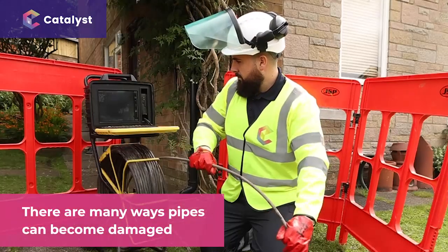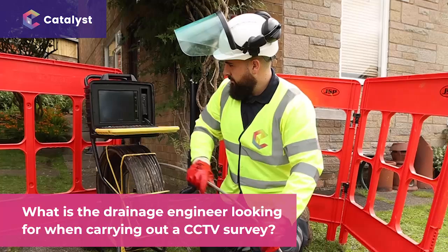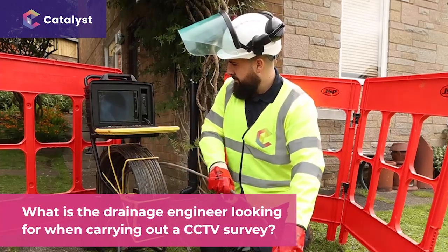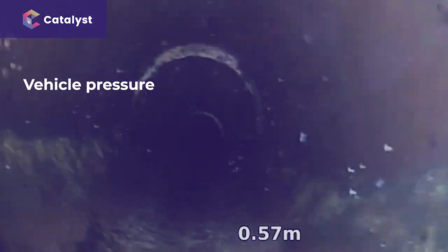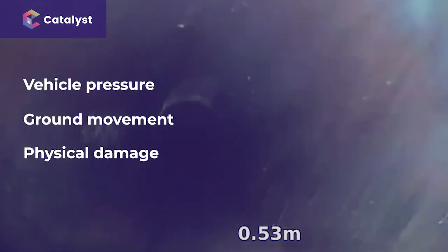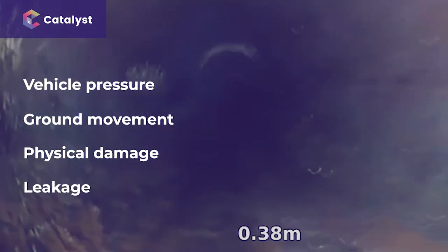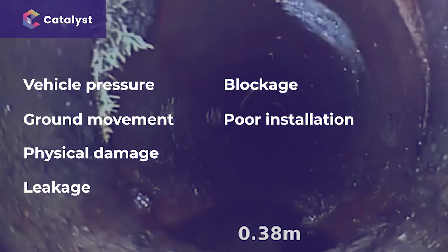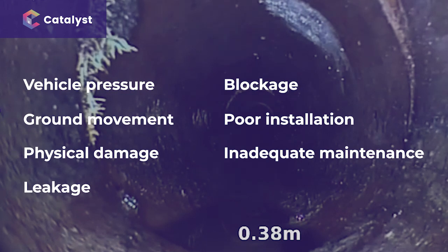There are many ways pipes can become damaged. So what is the drainage engineer looking for when carrying out a CCTV survey? Let's have a look. Damage can include vehicle pressure, ground movement, physical damage, for example by surface strikes, or different forms of misuse. Pipes can be undermined by leakage or during a one-off blockage. Damage can result from poor installation or inadequate maintenance. Pipes may have degraded through wear and tear.